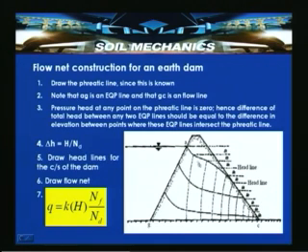So, in this case, if you look into it, the flow is taking place like this. The number of potential drops are numbered from this direction to this direction: 0, 1, 2, 3, 4, 5, 6, like this. And when it comes to the flow channels, there are 1, 2, maybe around 2.5 flow channels. So, by estimating the number of flow channels and the number of potential drops, and having known K, the coefficient of permeability of the soil in the bund or dam, we can estimate the rate of seepage which is actually occurring through this.